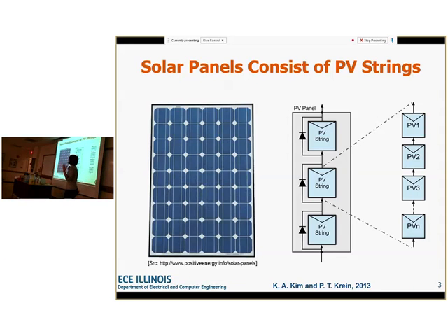So first of all, let's go back to the actual PV panel. This is a pretty typical panel, and when I look at this, I see 3 strings. You may not see that right away, but the way it works is each cell is about 1/2 volt, so 0.5 volts. In order to reach the voltages we need to connect to the utility, we usually put them in series. So all of these are strung in 1 string, and there are actually 3 strings here. It goes from the top usually back down, and there's usually a little junction box behind here. That's why they string it up and around, so you have the 2 ends of the string and you connect them in the junction box.